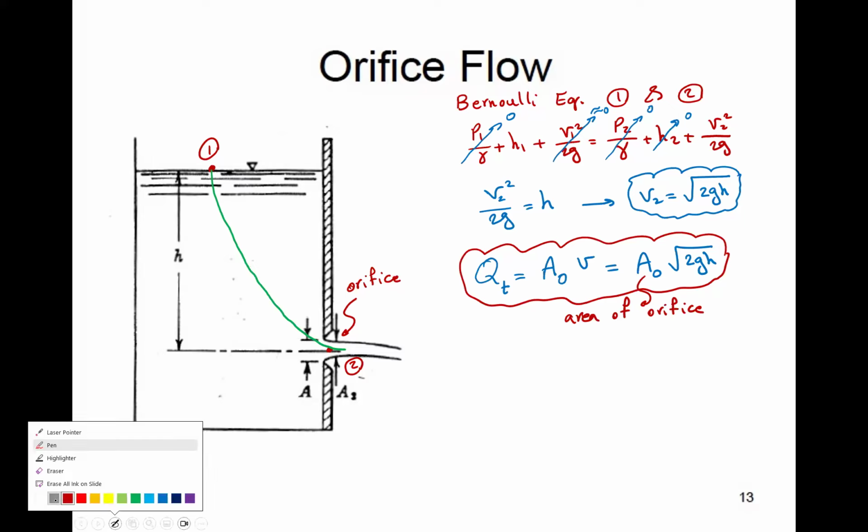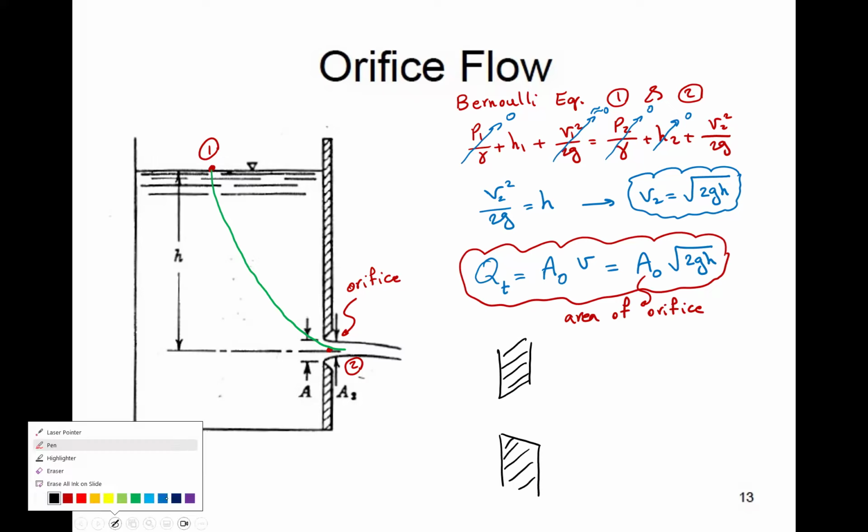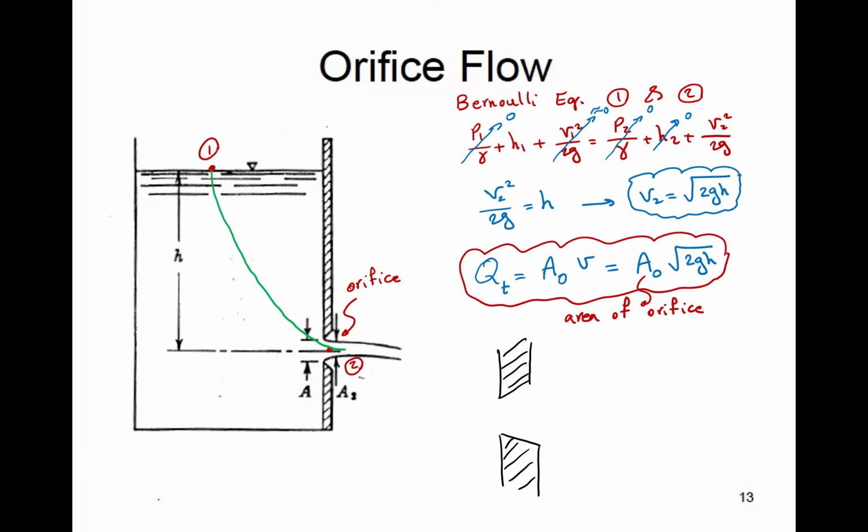As the flow exits the orifice, I'm going to zoom in and show a bigger picture of the orifice. This is what happens. The flow is coming in. It's impossible for the flow and the fluid particles to make a 90-degree turn at the exit of the orifice at one section, one point. So in reality, this is what happens. The flow is coming in, turns around, it continues to accelerate a little bit. The same thing happens on the upside and continues, something like that.